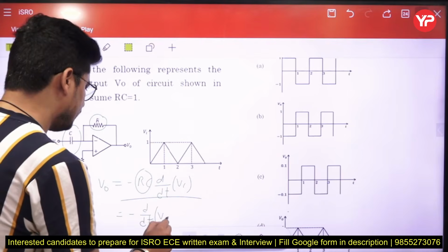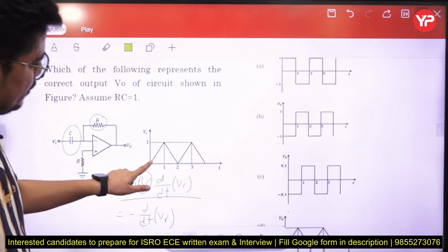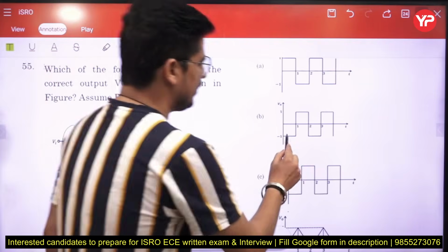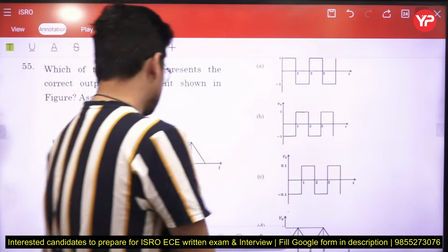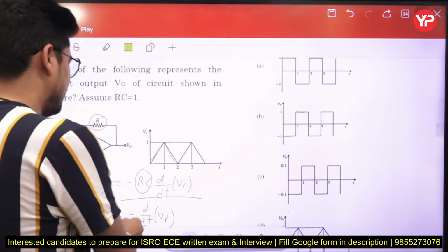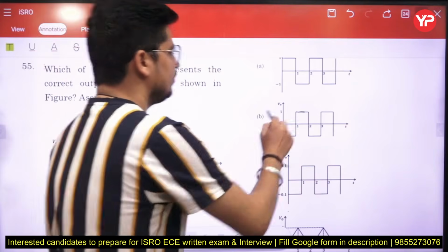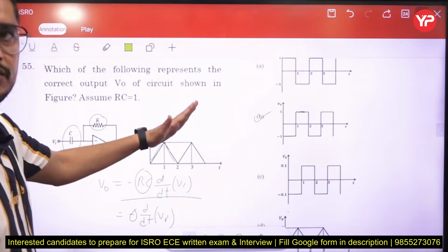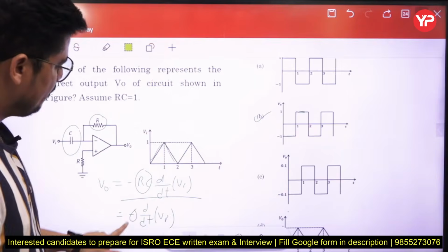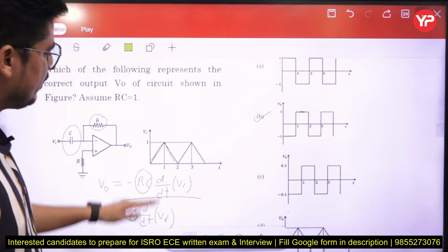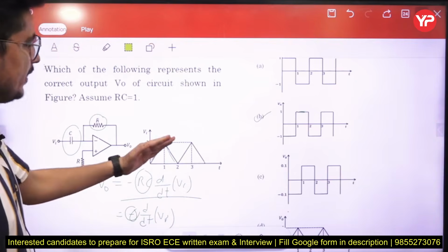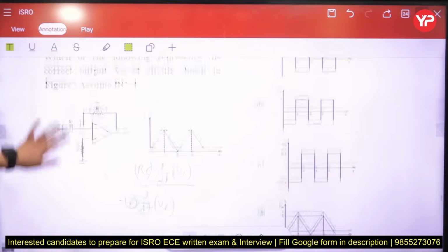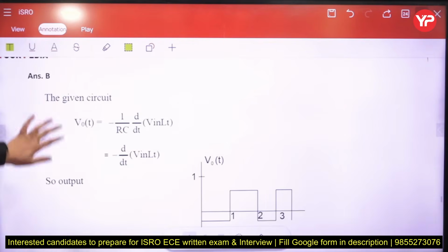of the input wave. So when you take the derivative, this line has a slope 1, that is going to be -1. Then in this cycle, the slope is negative, then minus is outside, that is +1. So the answer will be B here. You have to take the derivative; only the derivative will give you the slope. This slope is positive, because we already have a negative sign outside, that will make that -1, that is plus 1. This is the question from the GATE exam, last GATE exam they asked this question, right?